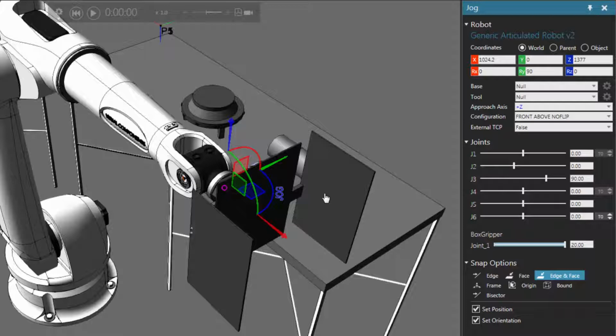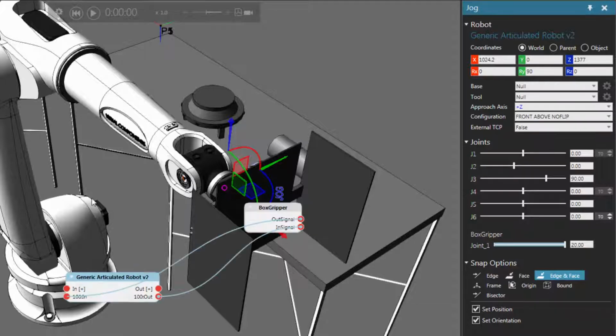In some cases, you may not want the robot to import a joint from a tool component. For example, if I go back and show you the signals, you can see that there is a signal in the tool that's mapped to a signal in the robot. So this is probably modeled to where the robot sends a signal to the tool component to maybe close its plates. So in this case, you probably don't need joint 1 to be imported.